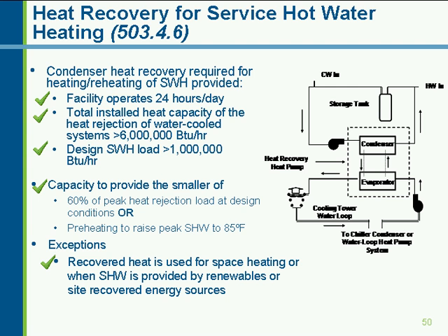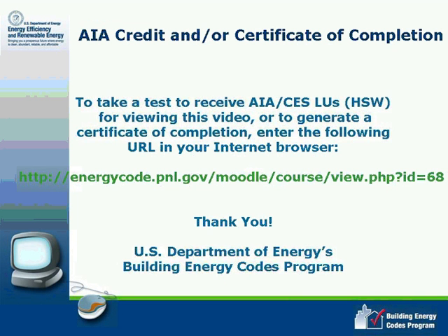Okay. Couple of questions, it looks like, about duct insulation. Is the space above a ceiling used for return air considered a conditioned space? Does the ductwork need to be insulated? Well, if the space above a ceiling is within the conditioned boundary, the thermal envelope of the building, then it's considered conditioned space.